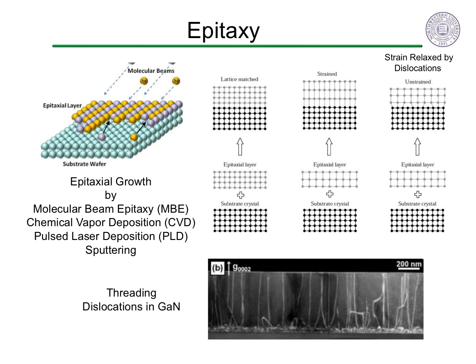For very thin films, the strain energy is small, so the films are easily strained, which can give different properties. Strained silicon is becoming important for semiconductor devices. Depositing silicon on a silicon germanium substrate with a larger lattice constant strains the silicon, which increases the electron and hole mobility by decreasing the effective mass and reducing electron scattering.